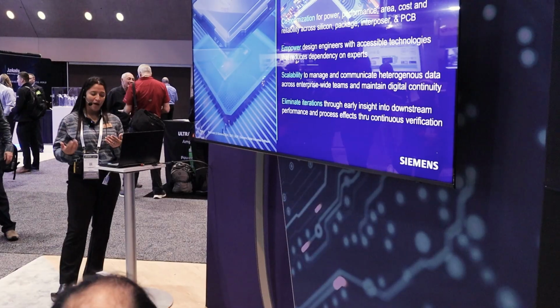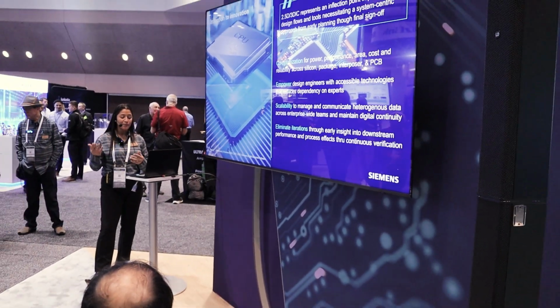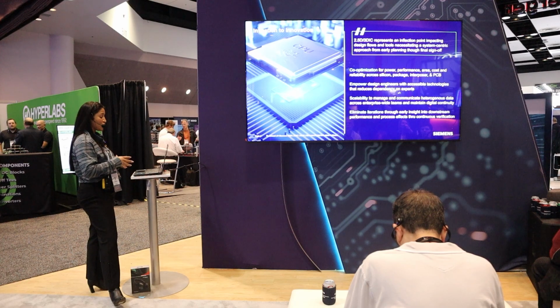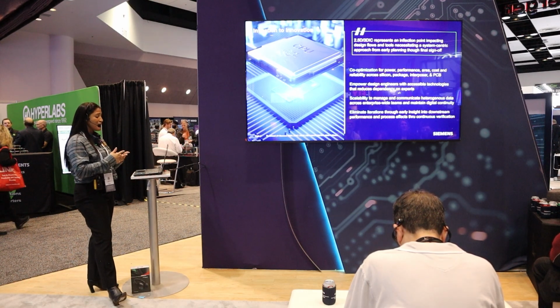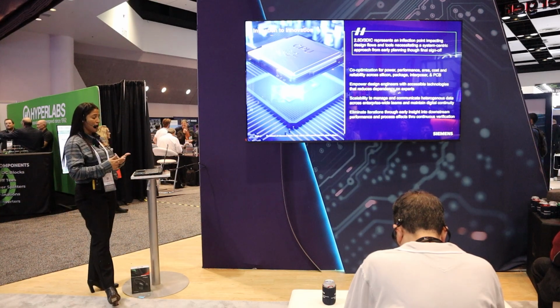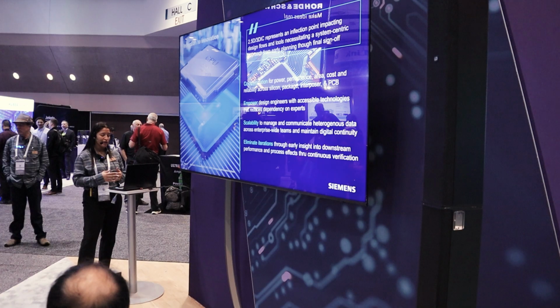And part of this is how do we empower the design engineers to find and fix obvious issues, right? So we're freeing up the experts to focus on a little bit harder problems. How do we look at process-related issues, to metal density and balancing, or how do we look at IR drop issues to enable the people doing the frontline design, without going through a lot of unnecessary iterations.